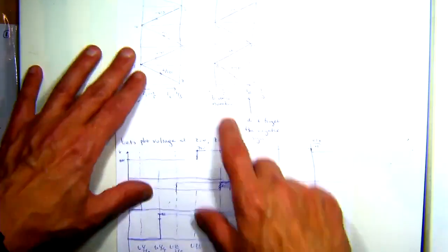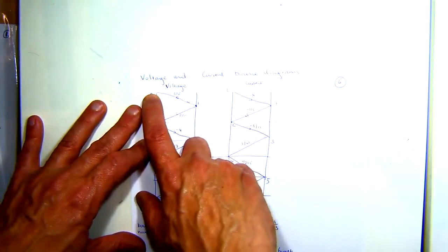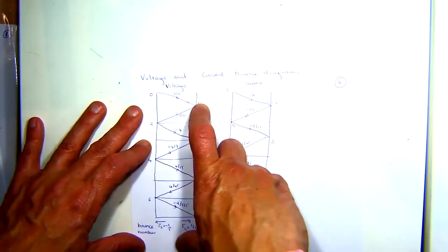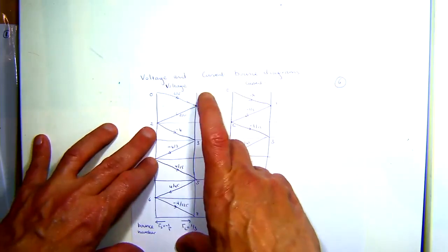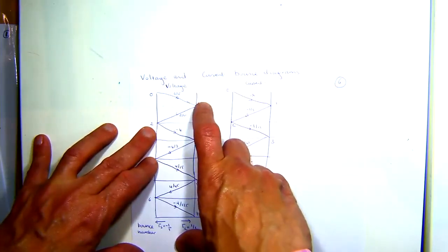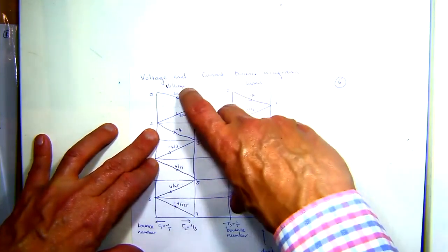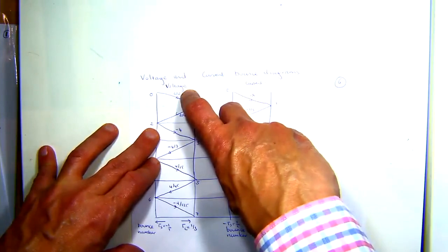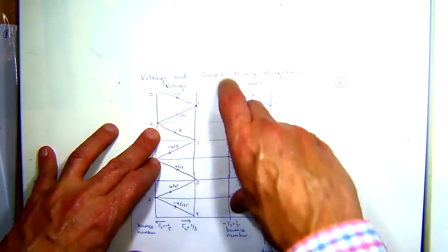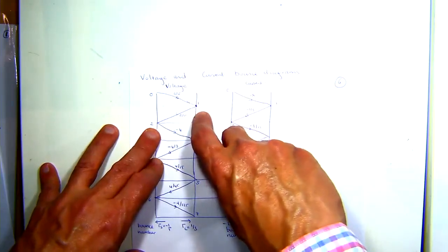So essentially what happens is we've got the voltage wave, it goes from the source to the load, I apologise for that, hits the load, works out that it doesn't meet the boundary conditions, and we get a reflected wave. Since the voltage of the generator remains there and it's not transient, we get the addition of the 60 plus 20 volts. That's why we get 80 volts.